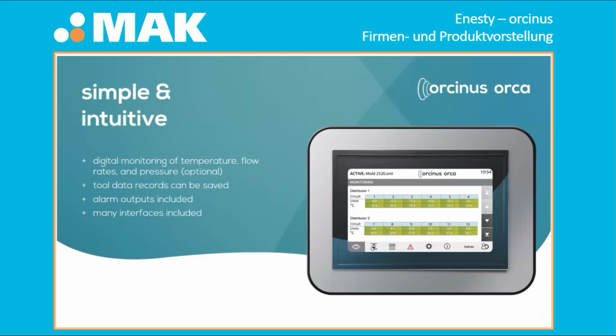Here, you can set your tolerance window. You know your process and which temperature you need to have perfect quality of your parts. You know the flow and temperature which make perfect parts, so you can define it. Here you can save the recipe for every single mold. So after a mold change, you just load the new recipe for the mold, in this case 2520, and you will have all the numbers stored.